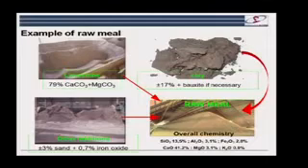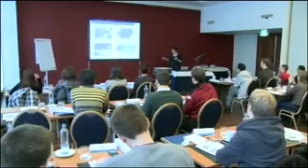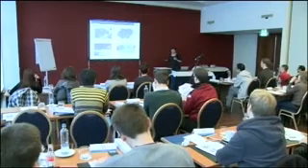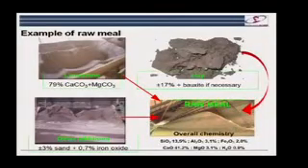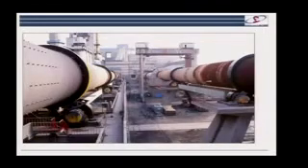The idea of putting them in this big hall is that with all natural materials, you have little tiny variations. So what you do is lay down your material in one direction, say this long direction, and then you take it in this cross direction. And by cross-cutting, this homogenizes the material, gives you a much more even blend. So this typically is the overall chemistry of a typical raw meal. And then that raw meal goes in the kiln.